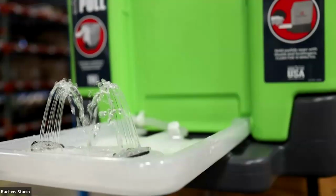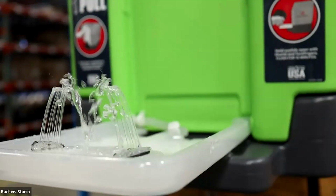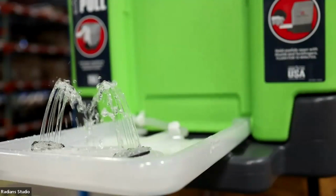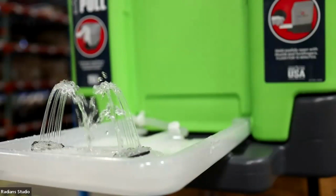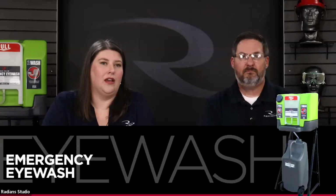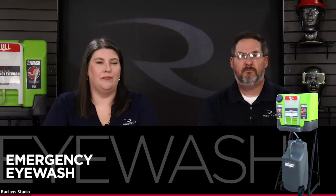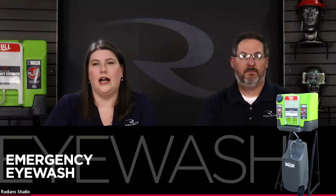This little video here just illustrates what the flow from an eye wash station looks like. You can see it's soft. That manifold was up at a 90-degree angle before being dropped here in this visual. Part of the requirements for eye wash stations is that the manifold be able to be deployed within 1 minute and with one hand, just again to not create any barriers to that injured party receiving some relief.